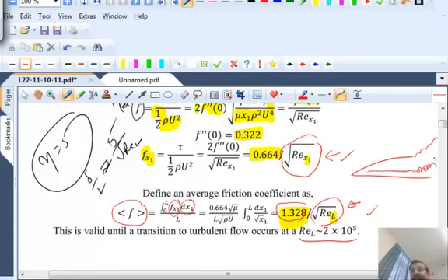The boundary layer thickness becomes completely different. Where that happens is roughly 2 times 10 to the 5, based on the length of the plate. So there is a certain length of the plate where you will hit that Reynolds number. Beyond that length, if the length of the plate is larger than that, the laminar boundary layer will become turbulent. That one can understand only by, again, stability analysis. So it's not 2100, but it's a much larger number.